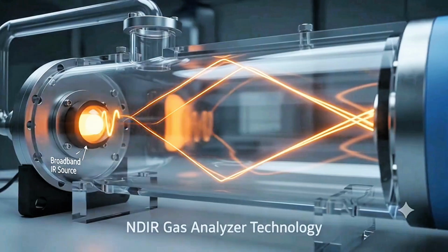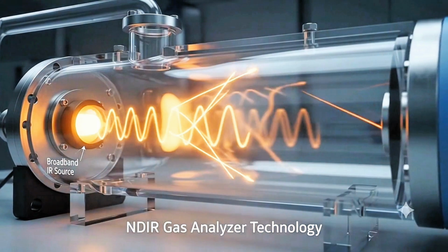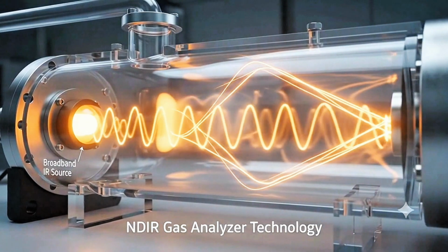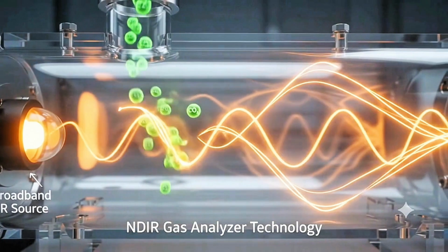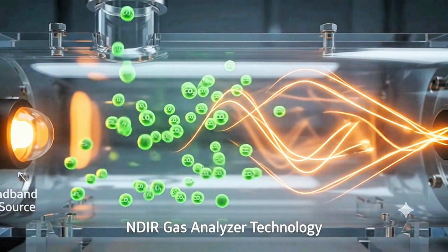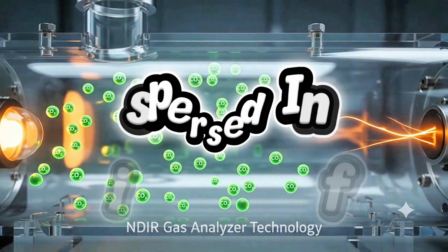Why we use an NDIR gas analyzer. In our plant, we constantly need to know how much CO, CO2, or SO2 is in the processed gas, at the kiln inlet, in the preheater string, or at the cooler. The instrument that does this job for us, day in and day out, is the NDIR gas analyzer. NDIR stands for non-dispersive infrared.